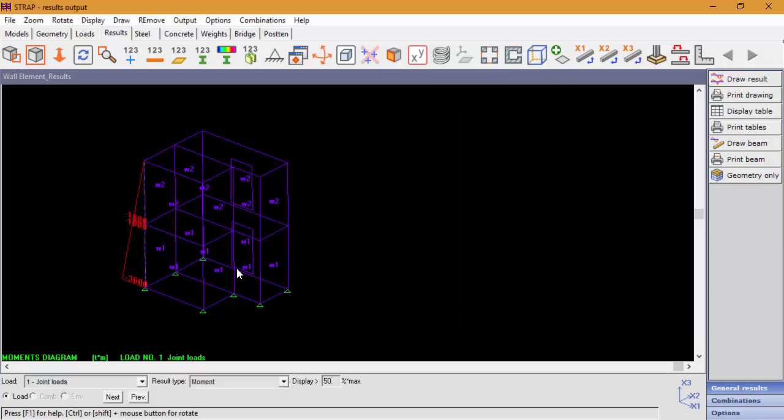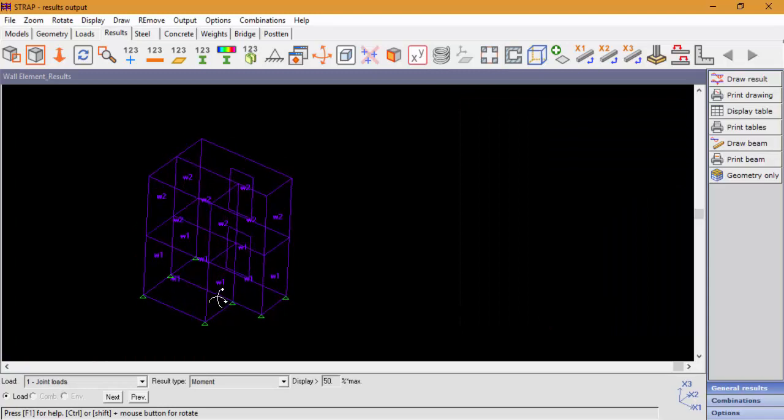We can see the moment result, 3,600 ton-meter. And the shear result is constant 600 tons. The result for perpendicular moment is very small, since we haven't defined any loads in the global x2 direction.